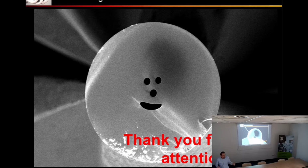But after, I think you cannot obtain all the profiles that you want. It's controlled by the refractive index of the crystals. So you have a kind of design that can be obtained depending on the time and the temperature, but it's strongly linked to the crystals you have obtained. You cannot decide on a design before the crystallization. You have to make different experiments and choose the temperature and stop your heat treatment when you have obtained the best profile. This is more based on experience.